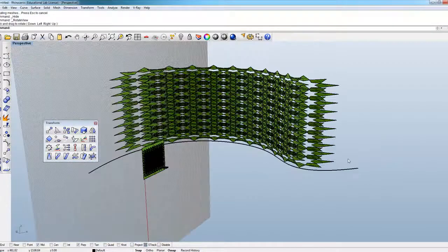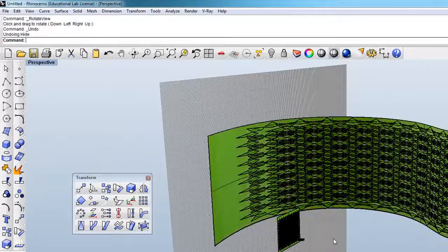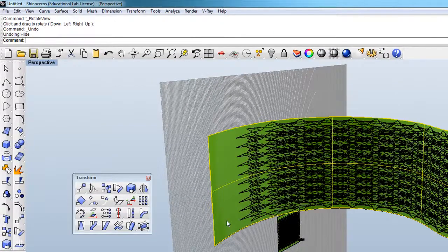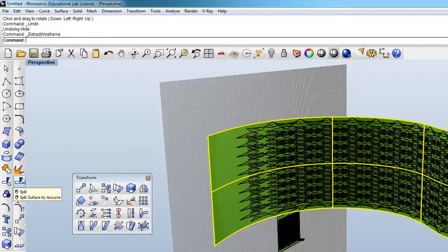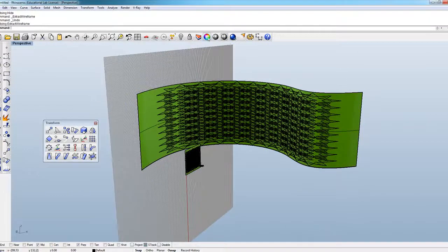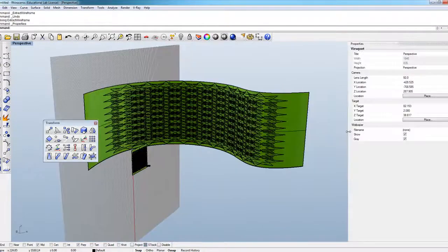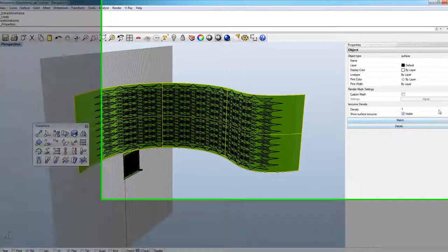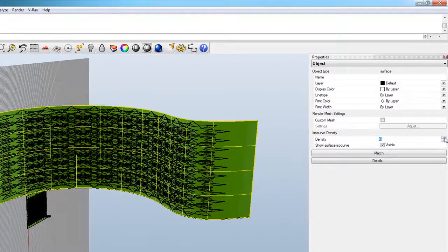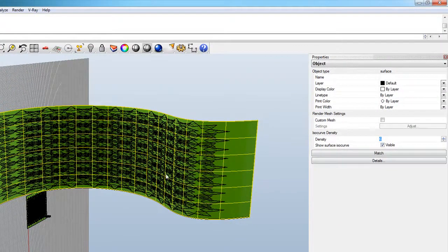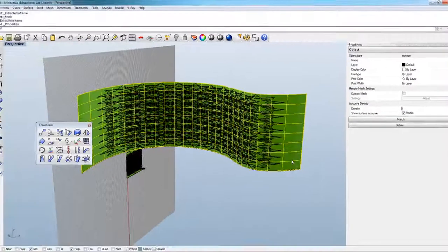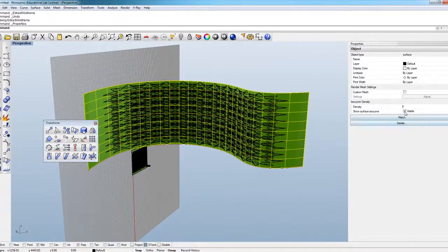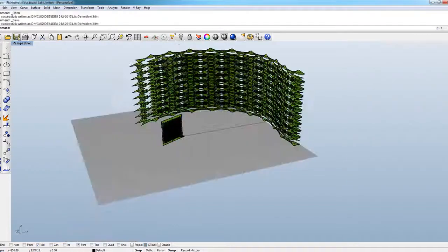The reason that the flowed pattern got stretched is because of the difference between the base surface and the target surface. In terms of the proportion, the base surface is pretty much like a square. The width and the length are very similar with a very narrow difference. However, the target surface is longer and narrower in terms of the proportion. Therefore, when the pattern is applied from the base surface to the target surface, the whole pattern got stretched.